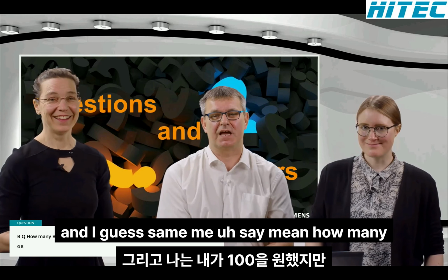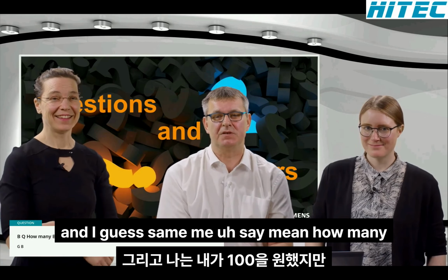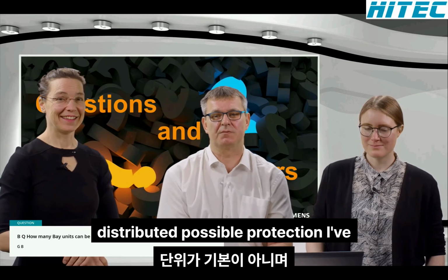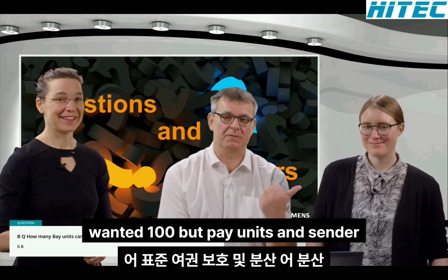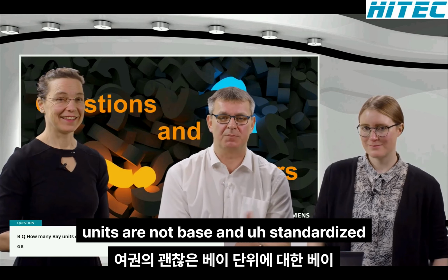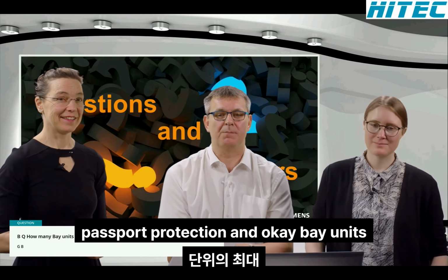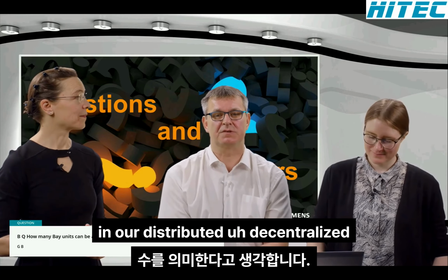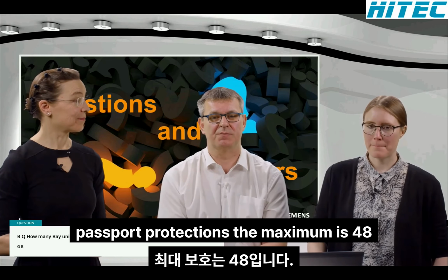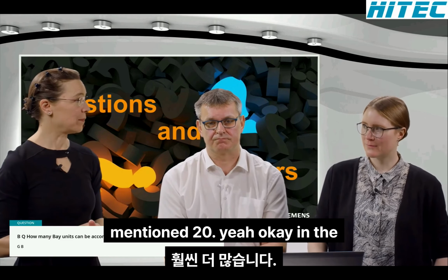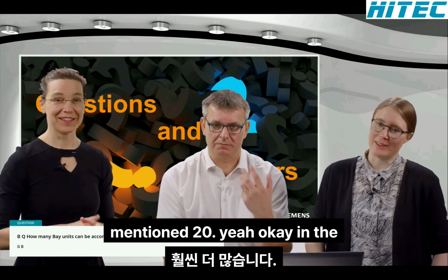And I guess they mean the maximum number of bay units in the distributed busbar protection. I'm not 100% sure, but bay units and central unit, and not base and centralized busbar protection. And okay, bay units in our distributed, decentralized busbar protection, the maximum is 48 now. Okay, that's even more than the mentioned 20. Yeah, okay, in a distributed setup.